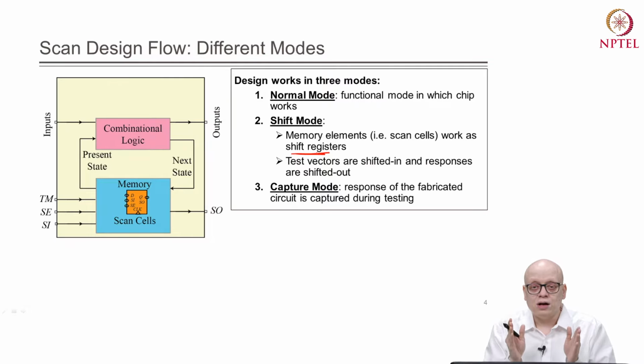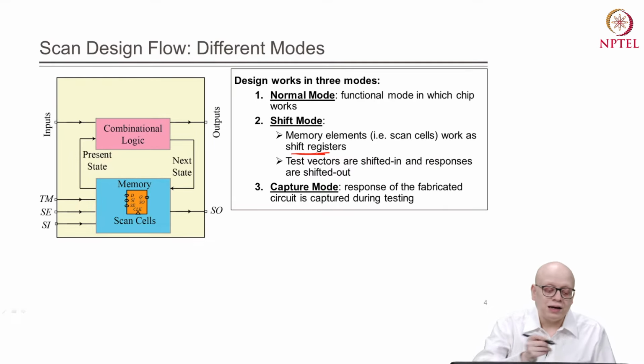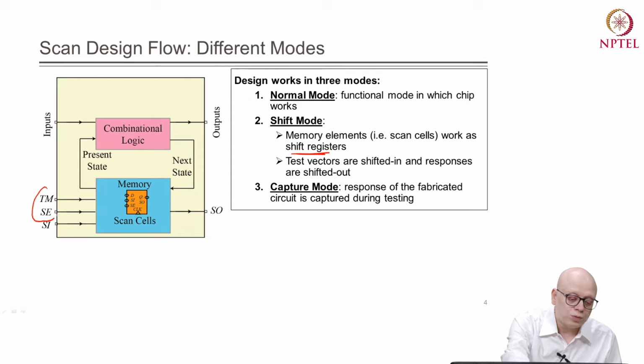So, when we are testing our circuit after manufacturing, during the testing of our chip, if we want to read the response of the fabricated circuit for the nets and internal signals in our design, then we take our circuit to the capture mode, right. Now, these three modes of our circuit can be defined with the help of the values at the input ports, right.